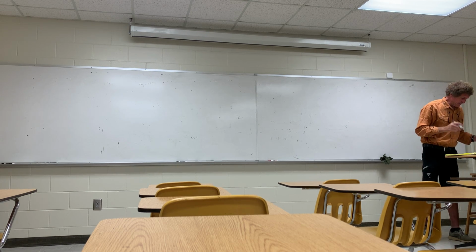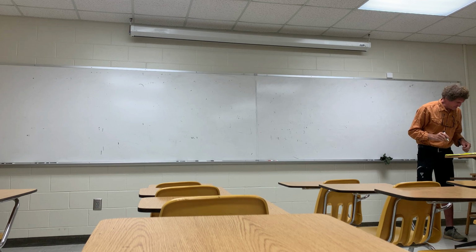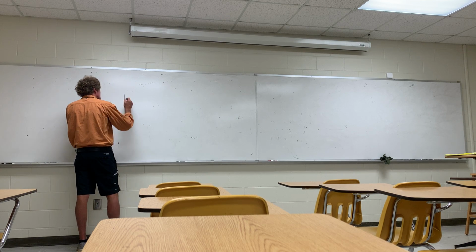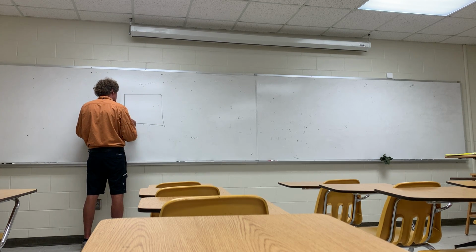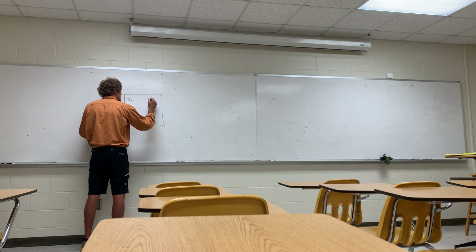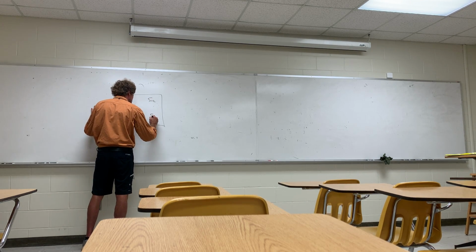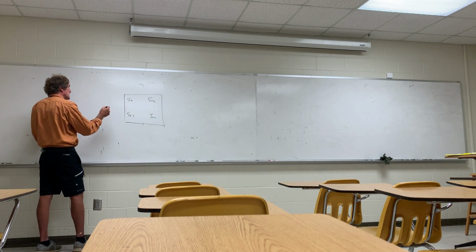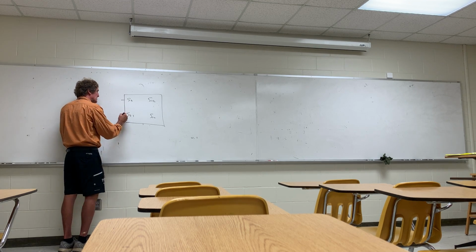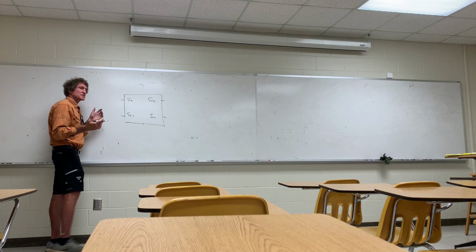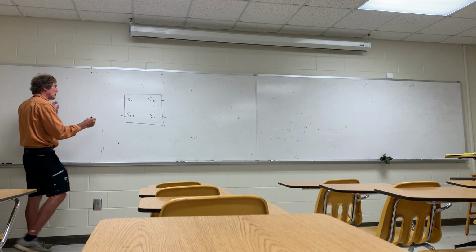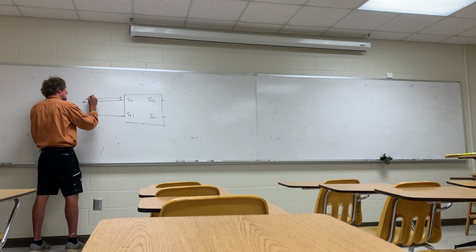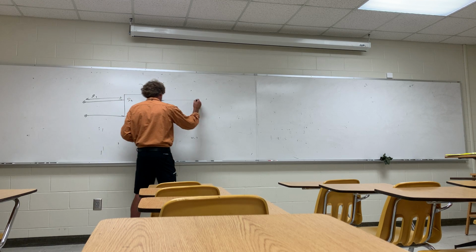Okay, so now shifting the reference plane on the bottom of page 566. In general, we'll just do it with a 2-port, but we can do it to N-port. If you have S parameters here, S11, S12, S21, and S22, those are usually magnitude and phase, at a given frequency. Now, if we measure the S parameters right at the port, but we want to extend it, we want the S parameters for something where we have a length of line L1 here, and another length of line L2 here.